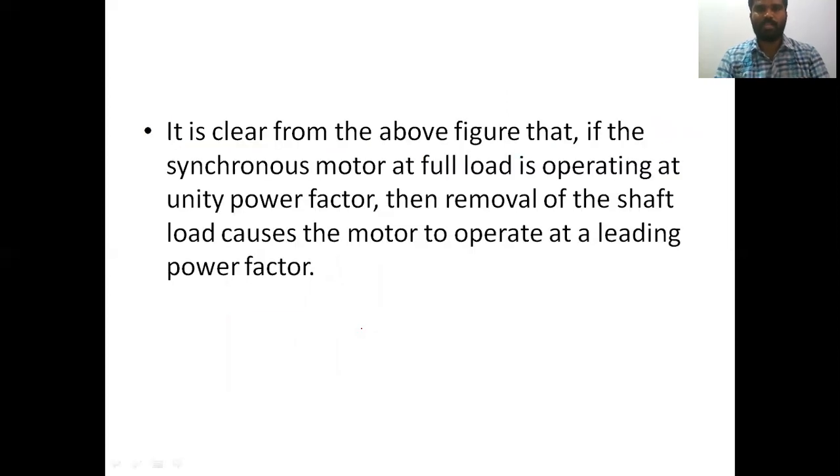So it is very clear from the figures that if the synchronous motor at full load is operating at unity power factor, then removal of shaft load causes the motor to operate at a leading power factor.